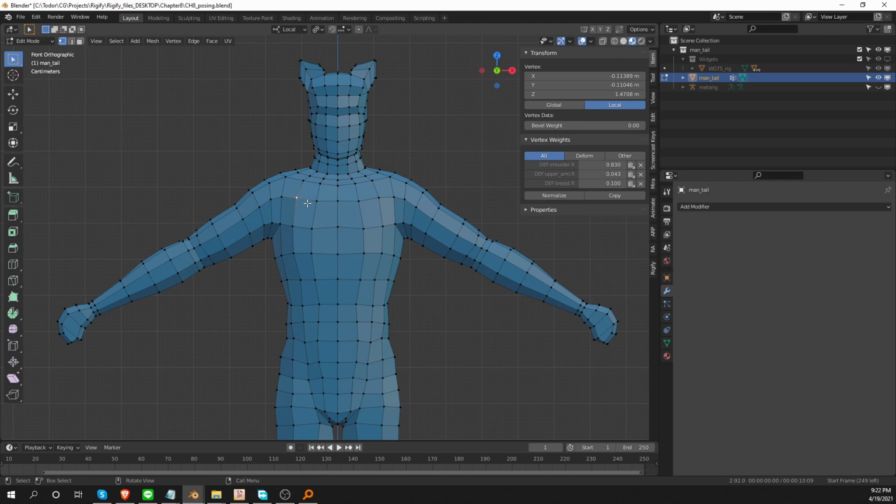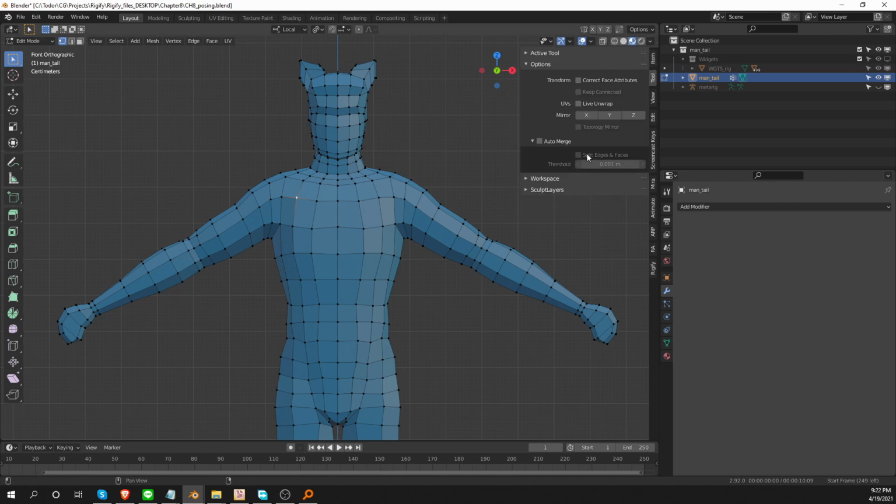And when that's the case, if I go to Tool and activate X Mirror and move some of the vertices, you'll see that I'm manipulating only the vertex on one side, but the vertex on the other side is being affected automatically. So far, so good. Nothing complicated, I think. But let's see how we can actually break this symmetry.